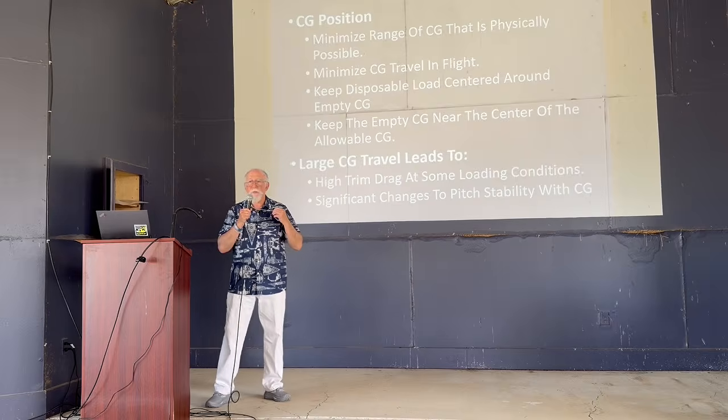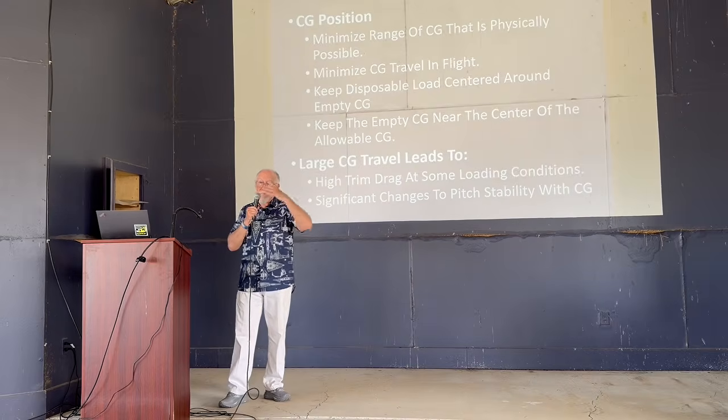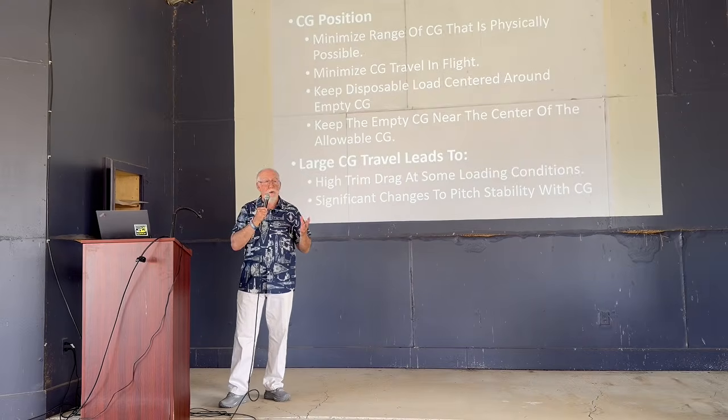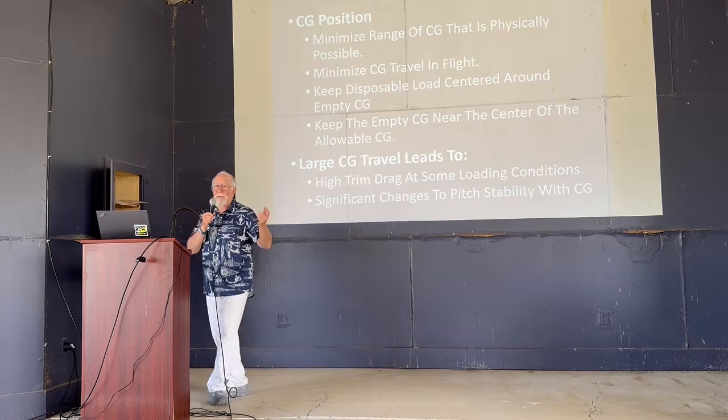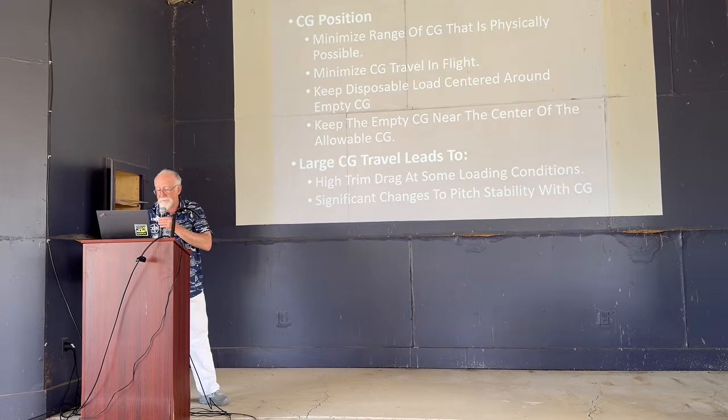And large CG travel, you can make it viable with a big tail and so forth, but it causes issues: tail weight, trim drag, various other things like that.